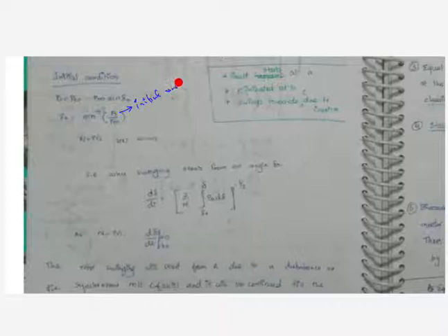So initial condition. It depends on how much power the generator is generating, right? If you look at the curve, this is the maximum power the generator can generate, right? This will be our steady state stability limit, and the system can operate at any point. It can produce 30%, 40%, 50%. Whatever that value is, this one, and this PM is our steady state stability limit, right?